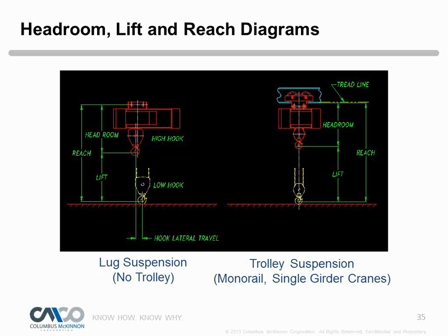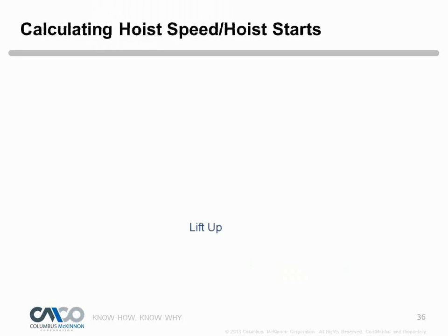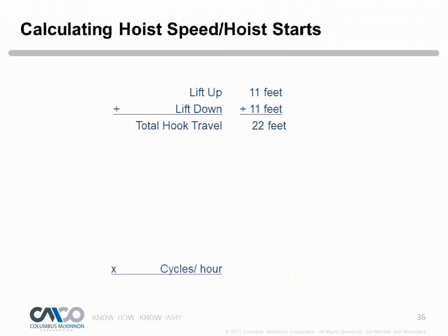Then your lift is how much lift you need, to where the hook goes to its utmost position, and then from the saddle of the hook to the underside of the beam is your headroom. That's what's specified when you look in catalogs, and how you're sizing the hoist. So when you're reading those catalogs, that's what you need. You need to be looking at that stuff and then subtracting out all your rigging equipment to be sure that we're applying it properly. Okay.